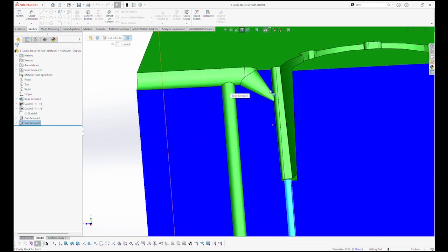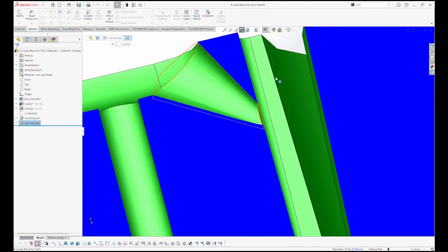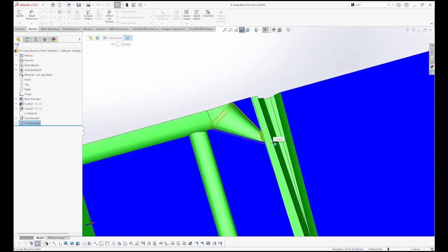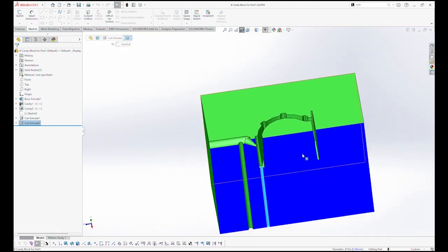And you can see this sharp edge. Now, when the ejector pins push the part out and also push the runner out, it will slice through the gate right here and automatically separate the runner from the part.